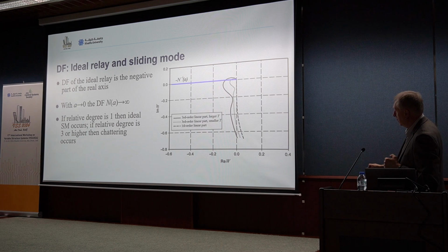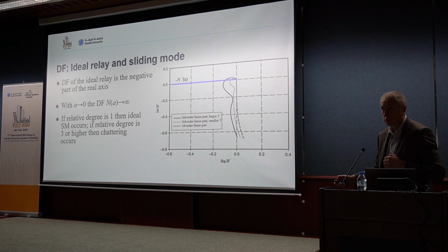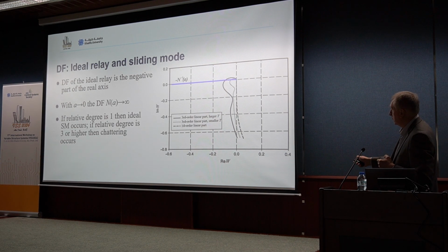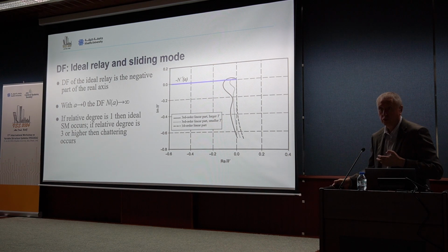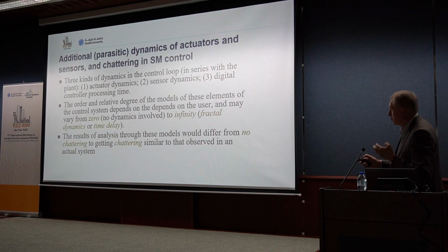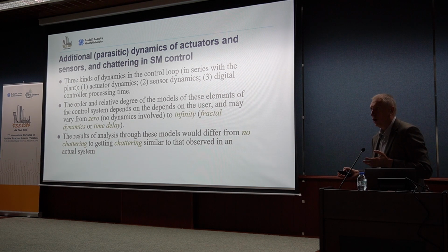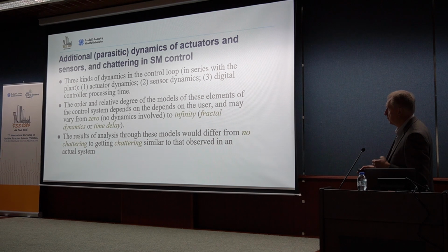But we definitely have an intersection point between the solid line and this blue line, or the dotted line and the blue line, and respectively this would be a point corresponding to self-excited oscillation, or this would be a point corresponding to self-excited oscillation. So we can solve the problem of finding the frequency and amplitude of self-excited oscillations.